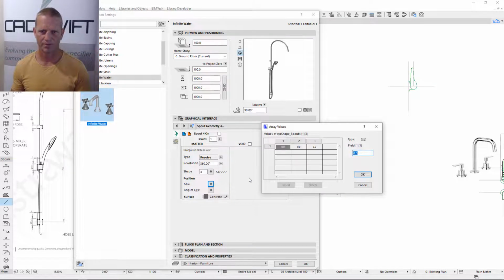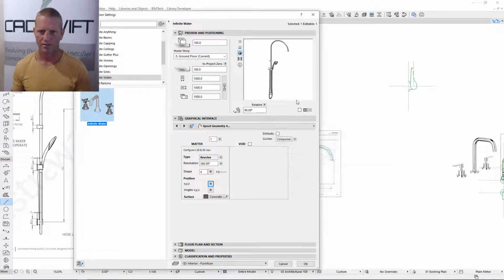So the positioning of the spout is going to be at, we've already got 700 and we want it to go up to 1070, 1060. So Z, and then we've been rotated 90 degrees. So this is the Z and that's the Y, I think. So we're at 700, 1060, so we want to go 360. And we want to have X is 0, and this is going to be out at 400 plus the center line of 30, so that should be 430, or I think it's a minus 430. Let's have a look.